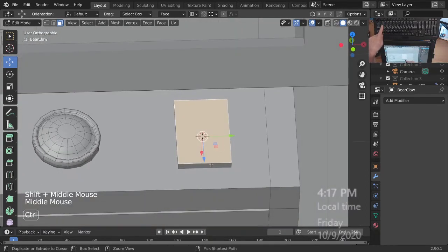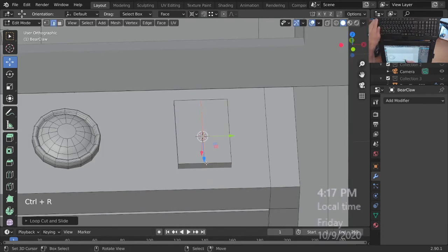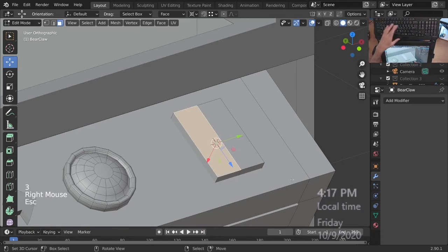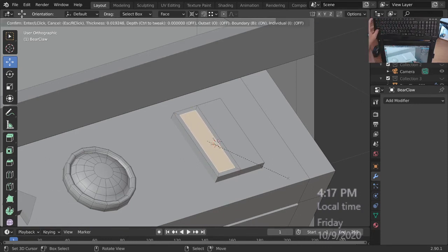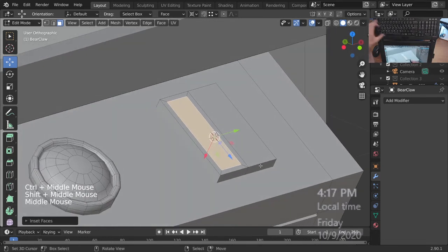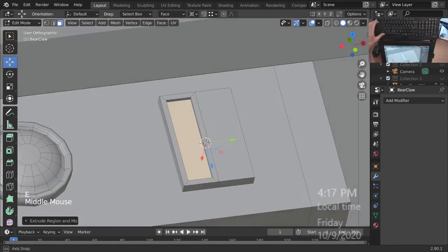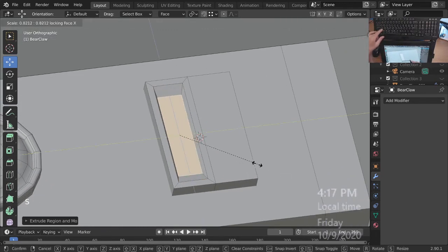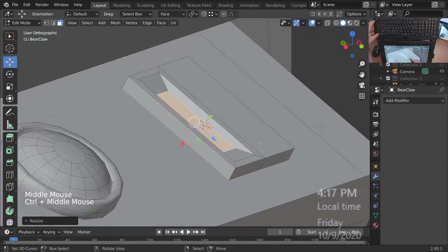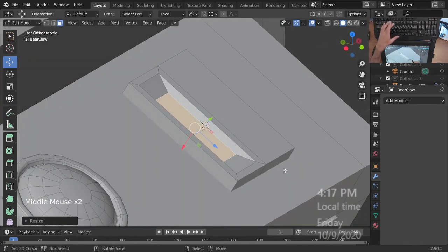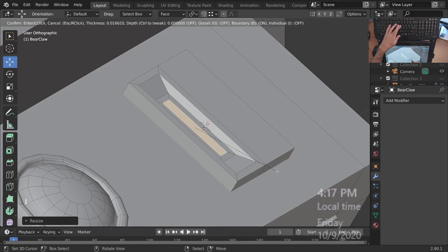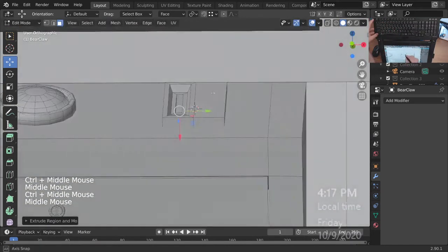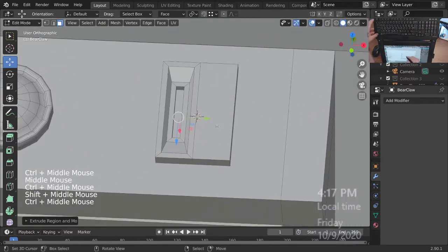So I'm going to go ahead and just cut in some loops first, cut a loop here, because I'm going to just use this for the coin slot. Inset 1, E, and let me go off the medium point. Let me scale Shift X, like that. And then inset again, and then extrude in. Those are big coins, so maybe not.